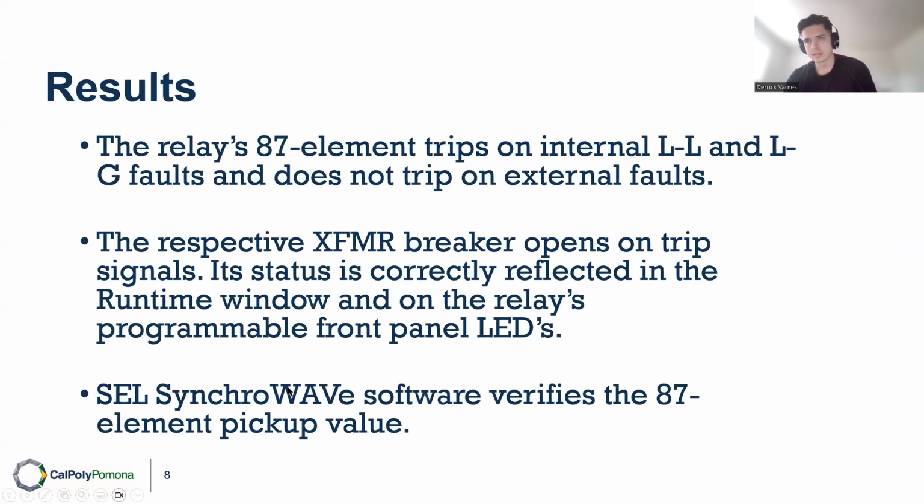A little more on that is that the relays have event monitoring, in which certain relay word bits can be used to trigger an event, in which the relay will actually record waveforms and bit values for a certain amount of time. We use this for making sure that our pickup values and certain bits were asserted correctly.